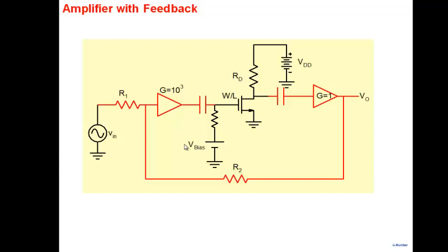And in multi-stage amplifiers, typically we may put negative feedback. Think of your common source amplifier as a part of an op-amp. In an op-amp, what will you have? First stage, a differential pair. Output stage may be something else, maybe class A, class B stages that you might have heard of. So it's a multi-stage amplifier.